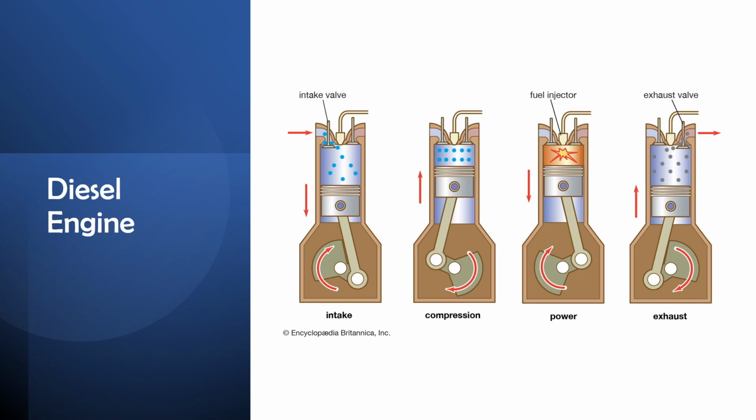So, a diesel engine operates on the diesel principle, involving the following steps. Initially, air is drawn through an air filter and compressed in the cylinder. Compression occurs solely through the piston. Without prior air-fuel mixture, fuel is then injected, and due to high temperature and pressure, self-ignition of the diesel fuel occurs in the cylinder. This self-ignition drives the piston downward, creating a power by expansion stroke and generating mechanical energy. Finally, the burned gases are expelled through the exhaust.